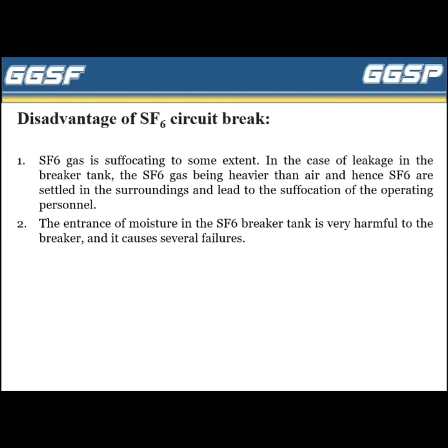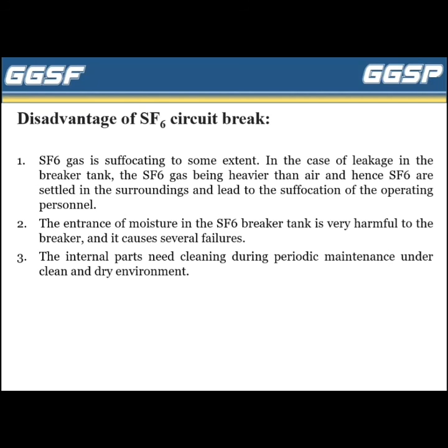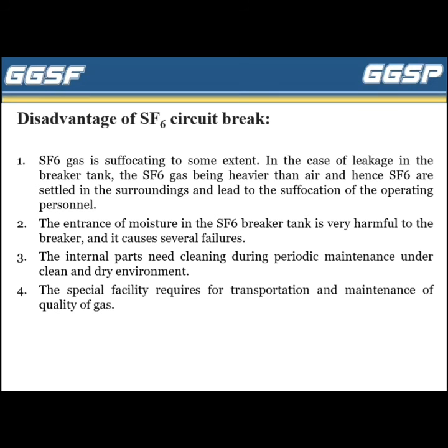The entrance of moisture in the SF6 breaker tank is very harmful to the breaker and it causes several failures. The internal parts need cleaning during periodic maintenance under a clean and dry environment. Specific facilities are required for transportation and maintenance of the quality of gas.